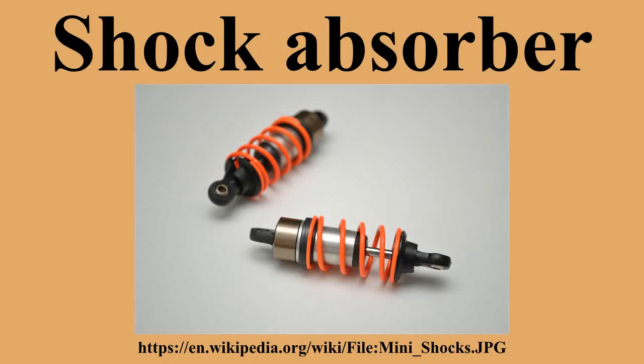One advantage of this type is that by using special internal valving, the absorber may be made relatively soft to compression and relatively stiff to extension, controlling rebound, which is the vehicle response to energy stored in the springs. Similarly, a series of valves controlled by springs can change the degree of stiffness according to the velocity of the impact to rebound.